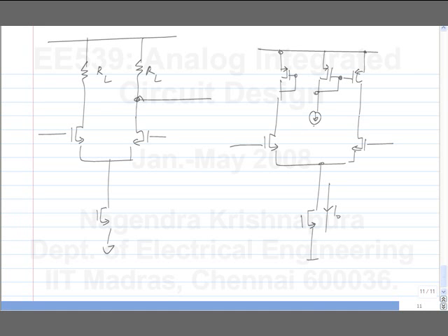You set it up so that in the quiescent condition all the bias points are fine. After that you apply an increment to the common mode. Then you look at the output increment and see what that's going to be. So the main difference between this and what we analyzed is that this is not connected to this node, but it's biased from an independent source of I naught by 2.